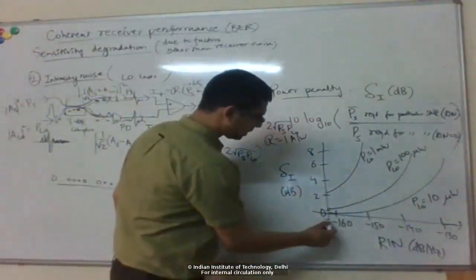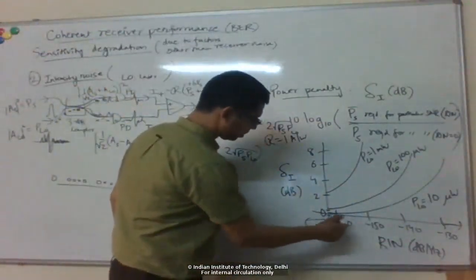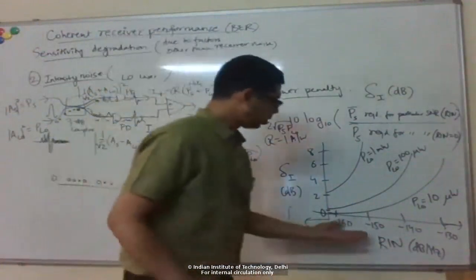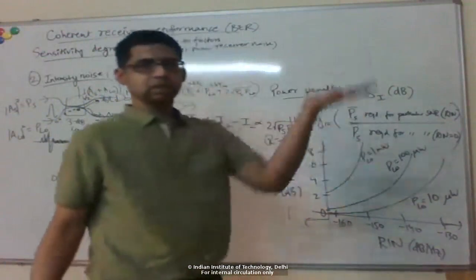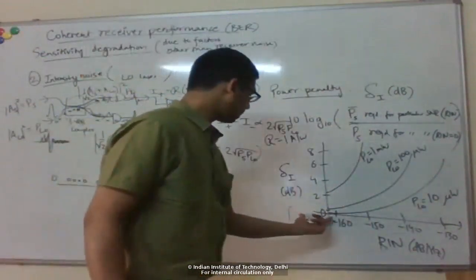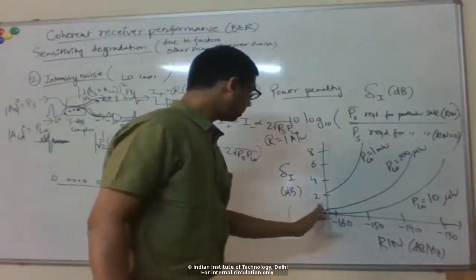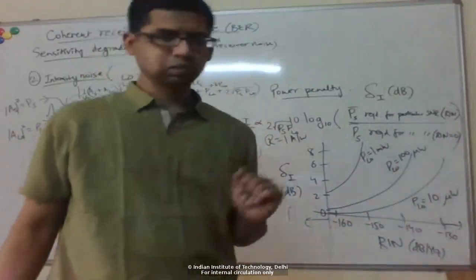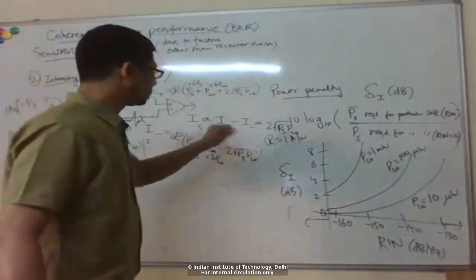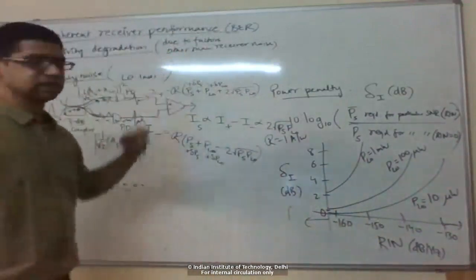So the shot noise limit is somewhere towards here. So the typical range you have in the laser is still above, maybe, I don't remember the exact number, probably it's 10-20 dB below still here. Okay, so you're still well above this ultimate shot noise that you can get to with balanced detection.